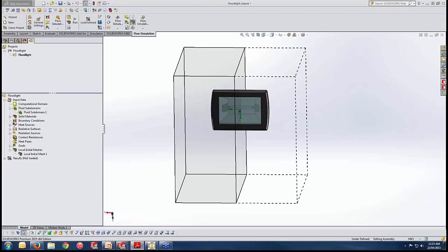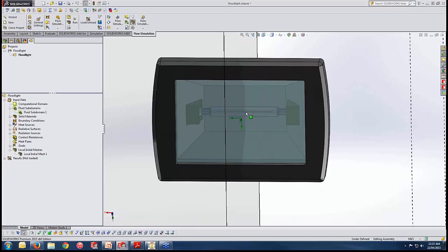Now, in the next step, we would like to specify the heat and radiation conditions. The first thing we know is that we have heat generation on a tungsten filament. Here is the component, and we would like to apply a heat source. Right-click, and you can insert a surface source, volume source, or import data from a model.